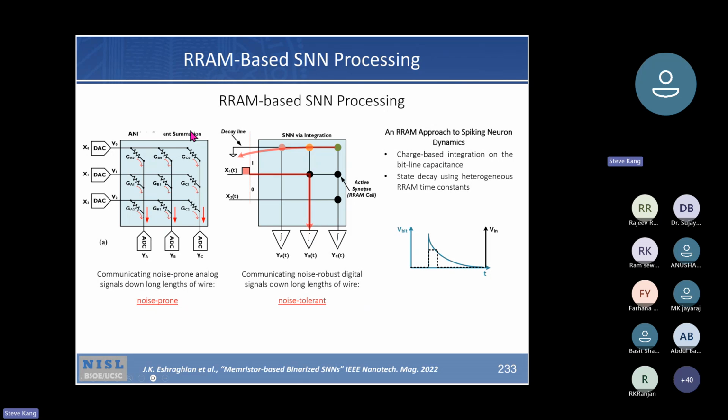So this is again a crossbar array. We are neglecting the transistor as a switch, but that's how it works. The input comes in and induces current, they add up, and then go through the integrate-and-fire model output. If it's not enough, there's no output signal. In this configuration you have a D to A converter and an A to D converter, but that's very costly. So the goal is not to use D to A to D type of converters.